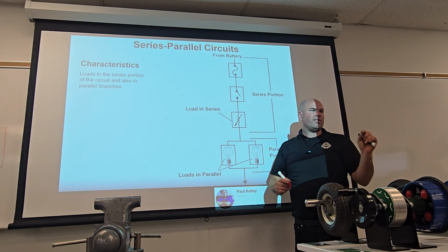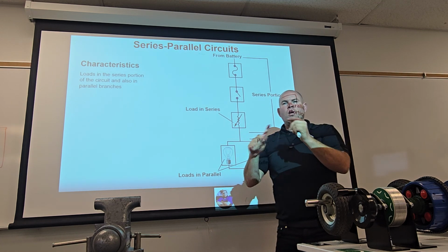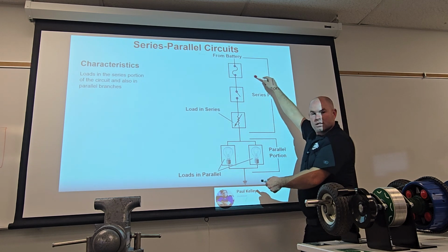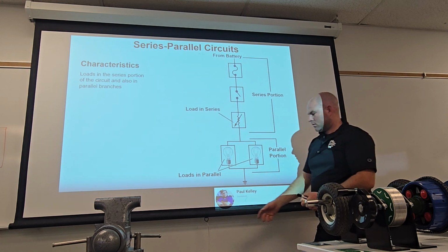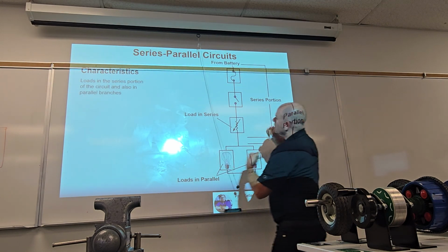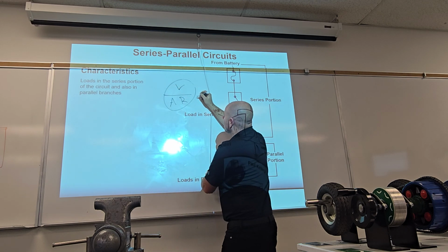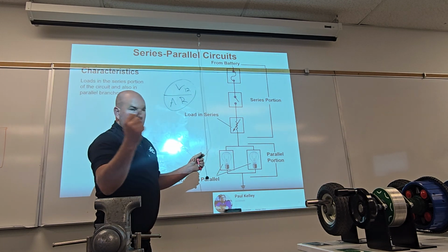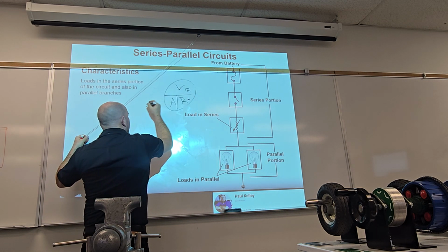Computers want to deal in millivolts. Remember millivolts? They want to deal in milliamps. I mean, very, very little tiny current flow. When I use a 4 ohm test light, I just made a circuit that bypasses the load that's only 4 ohms. Now, if we were to do the math, remember Ohm's law, we're going to do this. You remember Ohm's law like this, right? We'll do it right here. What goes on top? V, A, R. The volts is 12. The R, I'm saying I have a 4 ohm test light, so I'd make this 4. 12 divided by 4 is 3 amps.